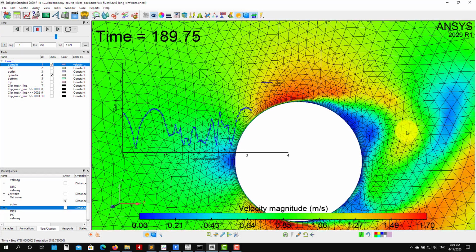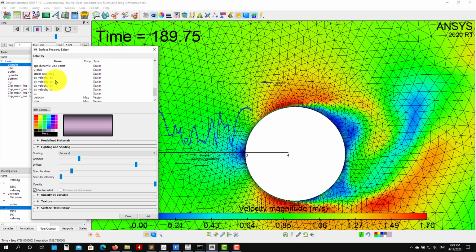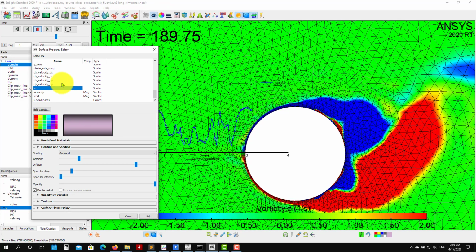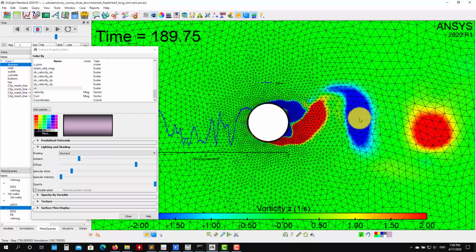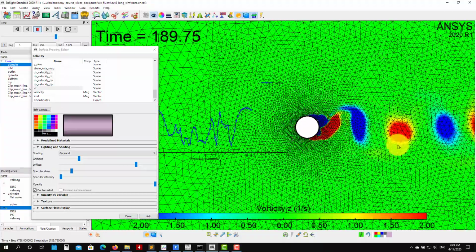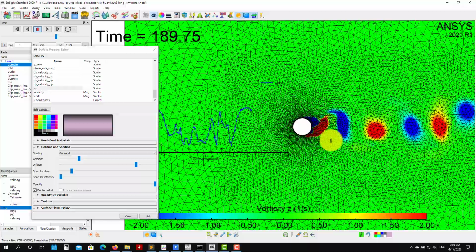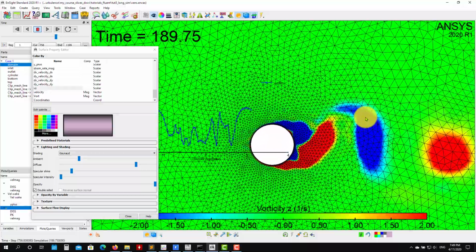And then as we look at the wake, let me look at the vortices here. Later there is also another very nice criterion to see if the mesh is resolving all the scales well. But we were talking about one slide on resolving a vortex: for the larger scales, the absolute minimum number of cells you need is about 5.